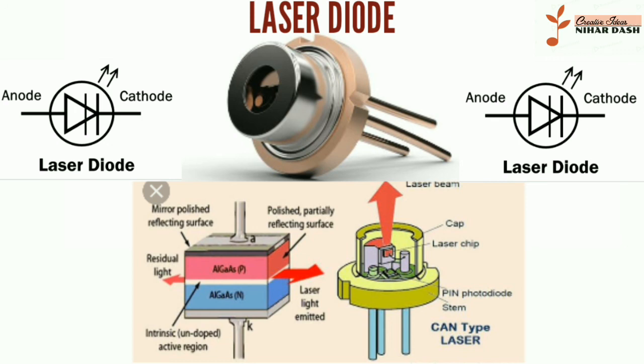As we have incorporated the whole junction assembly with a partially reflecting mirror, this will cause back and forth movement of the photons. Resultantly, this will generate more photons. As soon as the threshold is achieved, photons will escape from the mirror surface. A bright coherent radiation is emitted by the device. As at the time of stimulated emission, we are providing a photon energy to the atom, the emitted photons will be in the same phase with the incident photons, thus generating a monochromatic bright light.